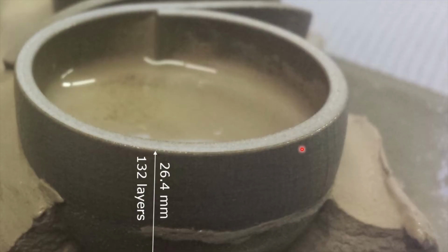Here you can see the washing process in progress. You see the nice surface finish of the cup. Here's the laser sintered body. That's the surface towards the laser. It is more shiny. You see a temperature difference here from the outer edge: the wider it is, the higher the temperature it has reached. And this is one disadvantage of the laser sintering process. It's anyway not ready to use, and you have a rather inhomogeneous structure.